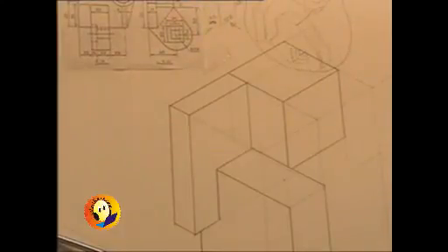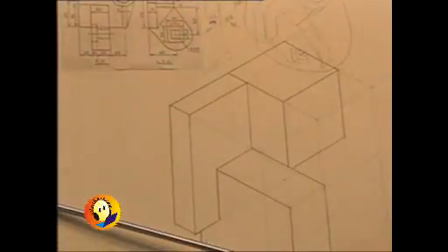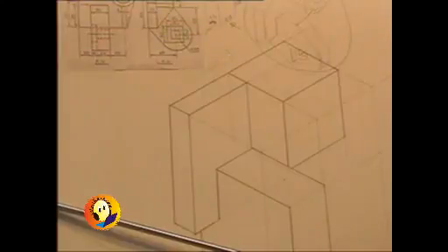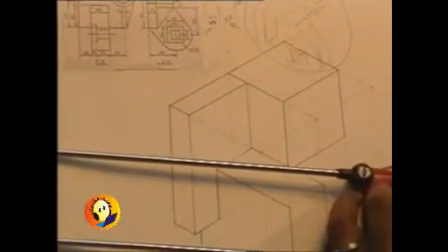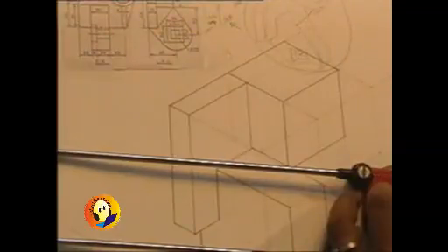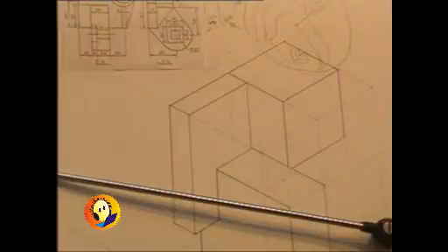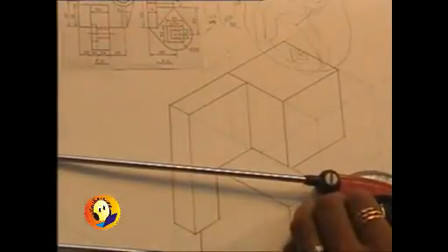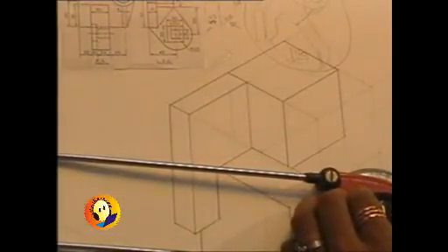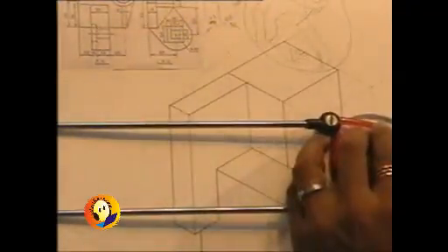No, it was 85, right? It was center to center 60, and then the radius above it, that is 85 from top, it has to be measured. And then the plate corresponding to it of thickness 15, which is seen in the left hand side view, can be marked.